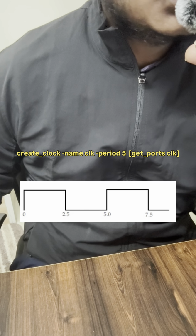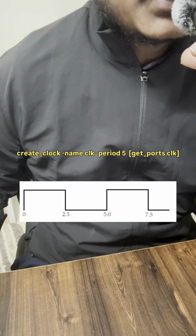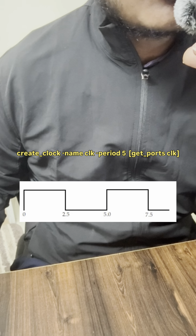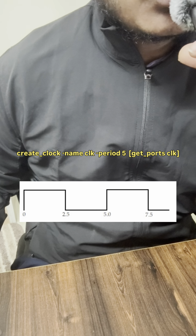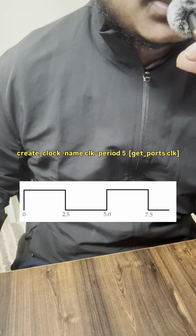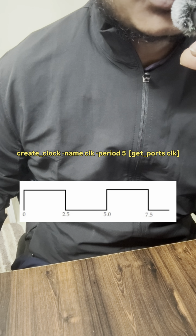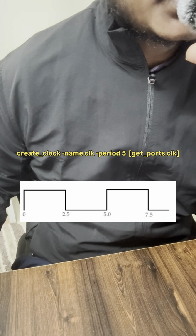Basically, what is create_clock? The create_clock command is used to define the clock signals in the design. The command tells the timing analysis tool what the clock signal is and what the clock source is. The clock source can be a port of the design or a pin of a cell in the design, typically part of the clock generation logic, and the timing period of the clock. A clock is applied. Let's see a simple circuit example.